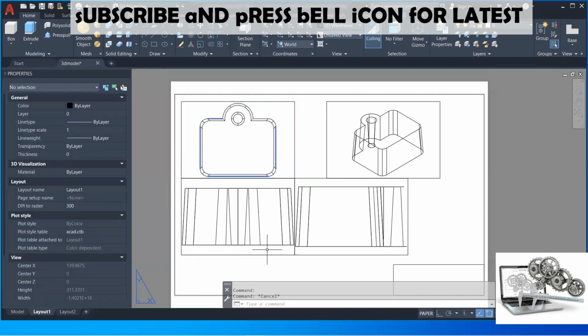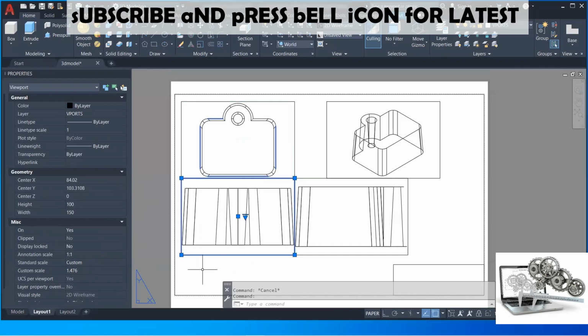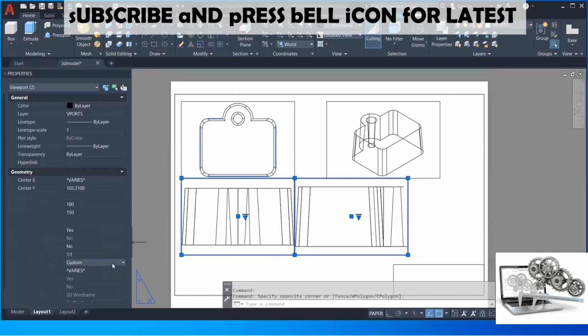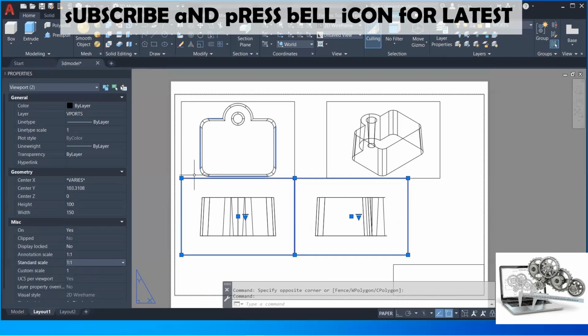The viewport boundary can be made hidden by using the layer commands. So don't bother about the viewport boundary currently. Just first give the scale factor and the height properly. Height we have given. Now we are changing the scale factor.